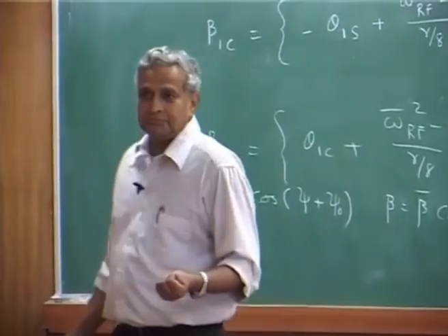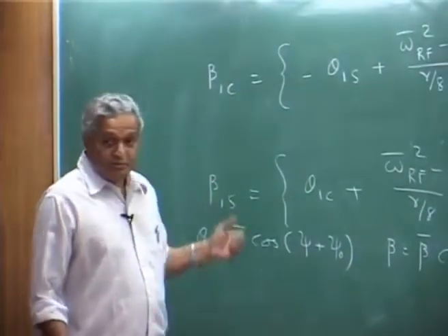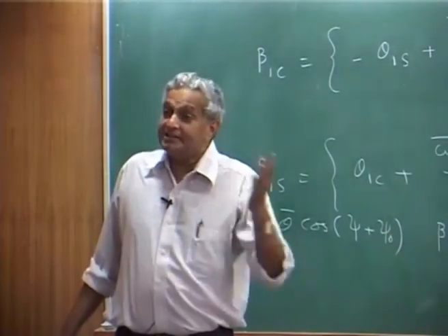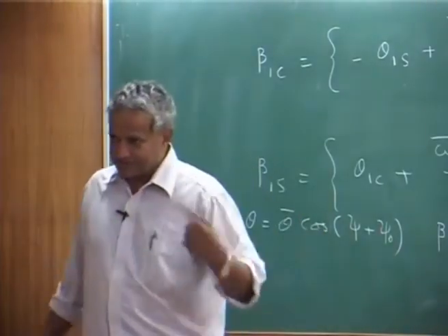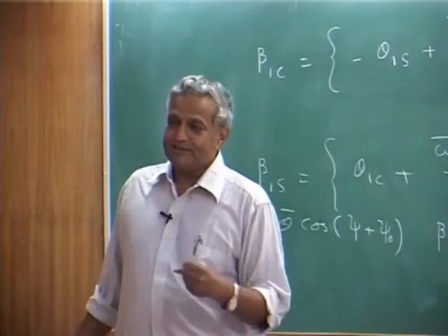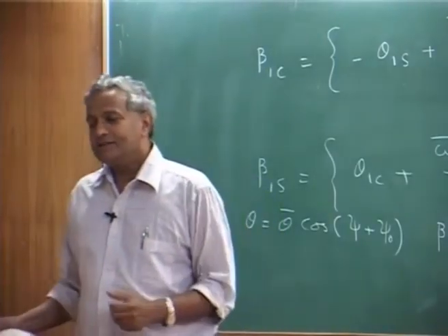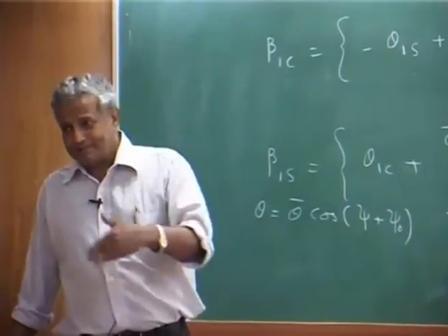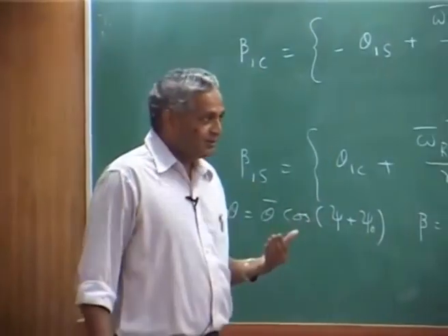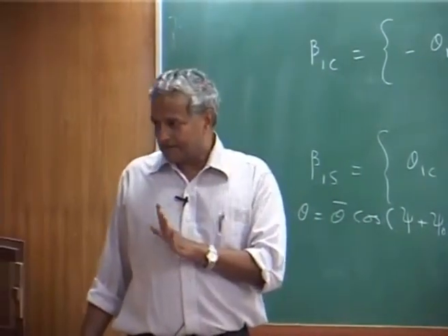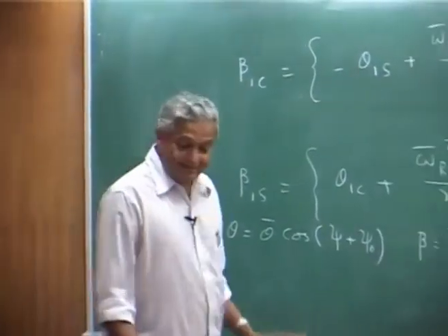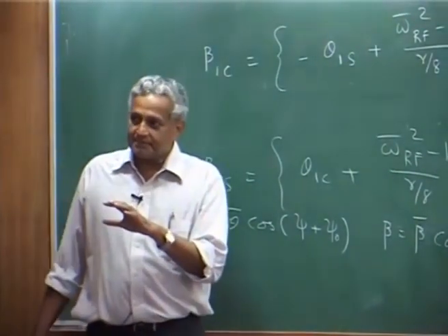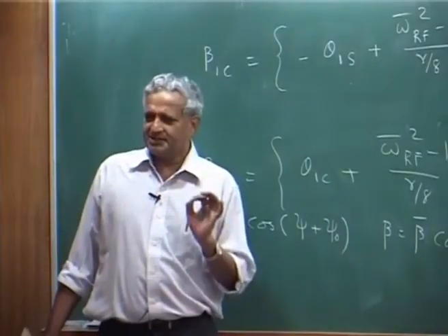So, what do they do? Because one input gives me two outputs basically, one intended, another one unintended. That means, I have to either compensate for that. Okay. This is where the flying requires skill. Now, you can have automatic flight control system, etc., many things, but that will aid the pilot to assist him slightly. Okay. This is one of the key, I would say, the difference between an aircraft and the helicopter, one of the key in flying the machine.